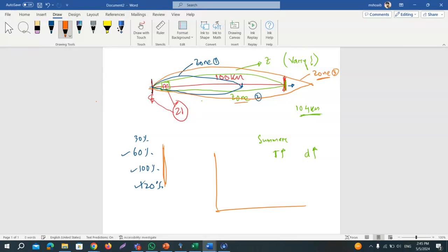We'll talk about these impedance relay characteristics more in the lecture class, but just to remind you, this was the torque region. Remember, this was the positive torque region. So for example, up to here is your zone 1, up to here is your zone 2, and here is zone 3. If any fault occurs in this position, it will be tripped by the relay by the mechanism of zone 1. If it is in this zone, this is your zone 2, and if it is here, then it will be your zone 3, and so on. I hope it is clear.